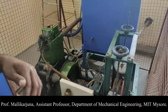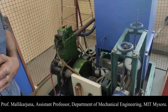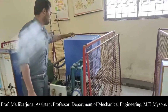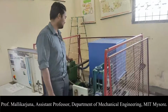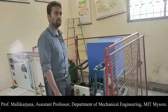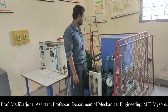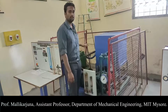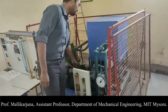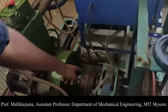We know this is a four-stroke diesel engine. In a diesel engine, only air enters into the cylinder. So air initially enters into this chamber, through which the air enters the engine cylinder. Thereby compression happens. Then the fuel injector injects the fuel, thereby combustion as well as the power stroke begins. Then exhaust happens. These are the four different strokes that are performed by the engine. Now the developed power will be transferred to the flywheel, and then the power will be transferred through the crankshaft.